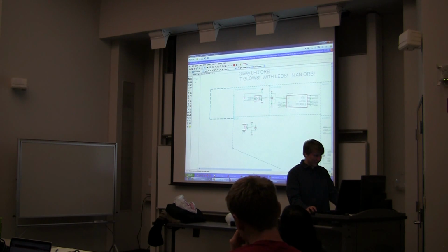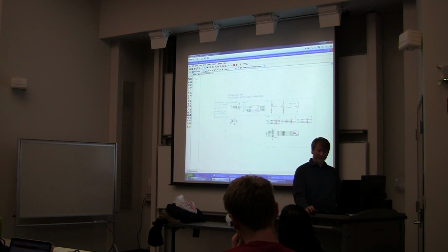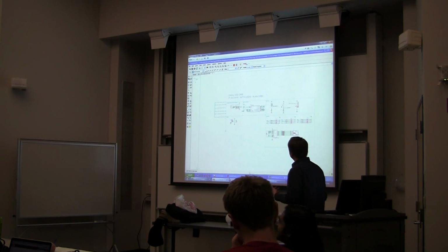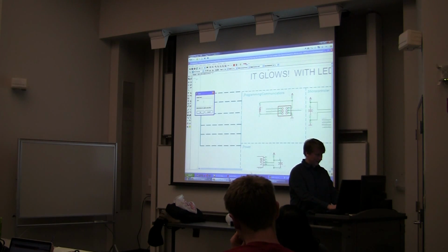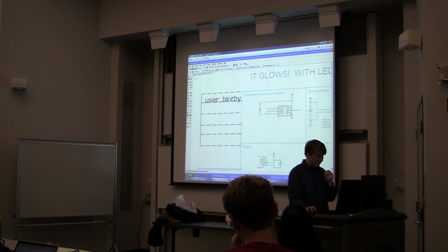So if you want to make your own little box of fields, you can make things arbitrarily pretty. Eagle is fundamentally not designed to make anything look pretty, so I'm not going to worry about it. But you definitely want to have things like, maybe that's too tall. Let's just use font size, that's better. So I can shrink the font size.